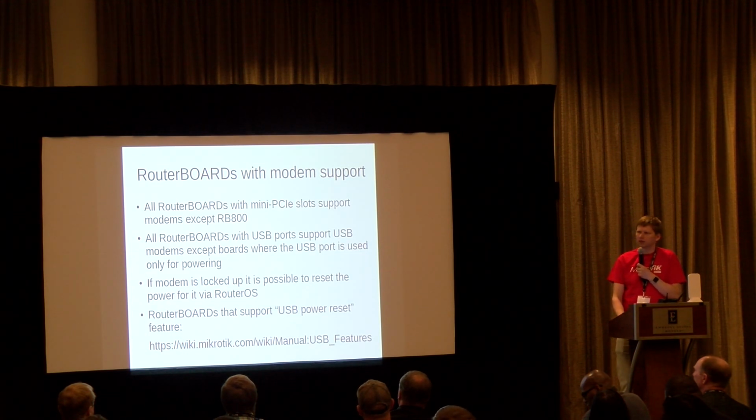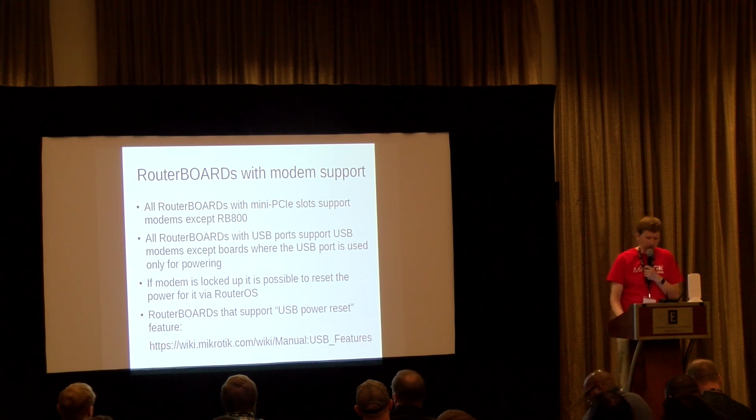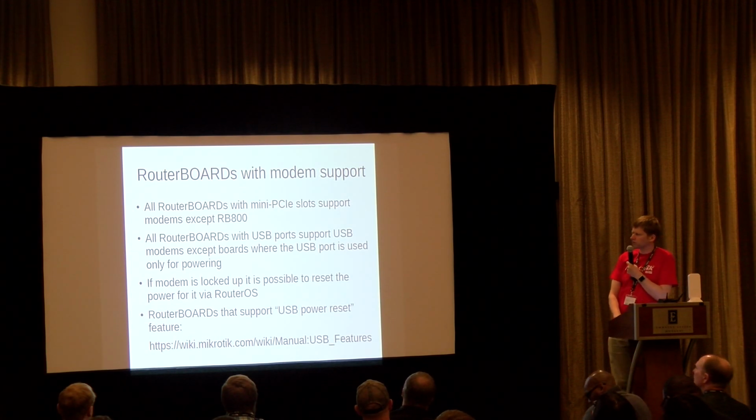Also, we have a special USB feature called USB power reset. In case the USB modem is locked up or not responding, you can do a USB power reset. It will turn off the power of the USB, and you can use that command to recover the state of the modem. So if you have that modem sitting in some remote location, executing this command will result almost the same as unplugging and plugging back the device. Also, to see which modems and which boards support the feature, you can see this wiki page.